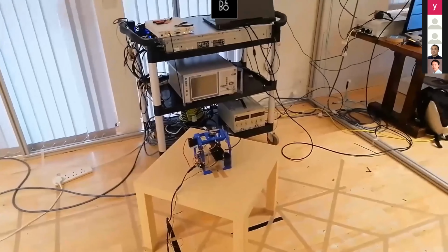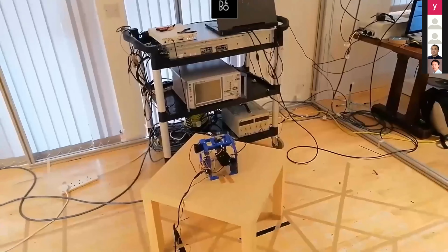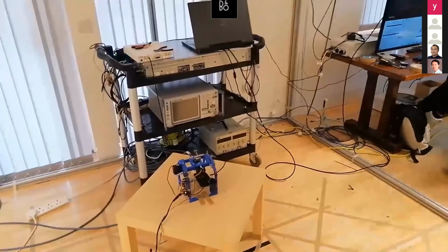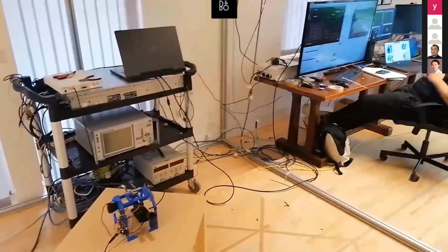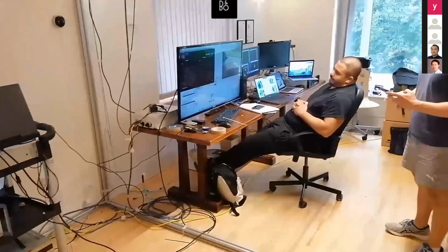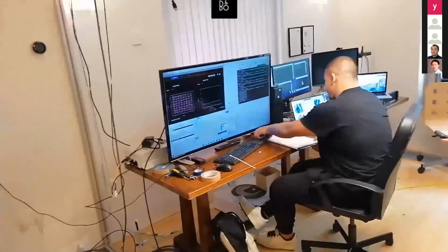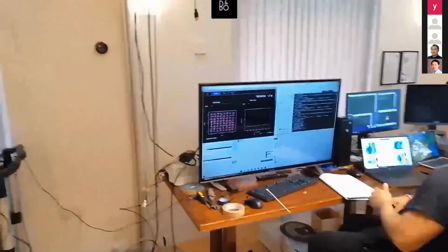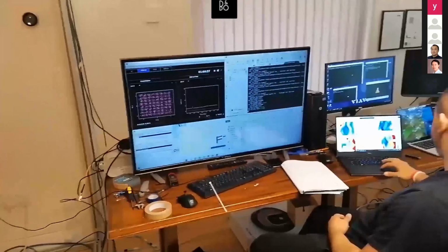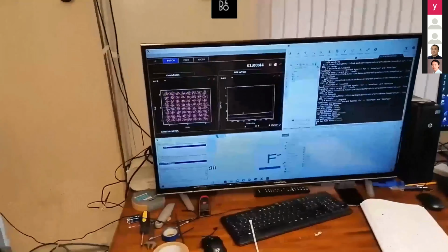The test receiver records 5G received signal strengths, QAM constellation diagram, mean and probability distribution of the error vector magnitude, the error vector magnitude evolution with time, the block error rate and throughput for the physical downlink shared channel, the physical broadcast channel, and the physical downlink control channels. Here you can see the millimeter wave recording being taken at tabletop height, 0.7 meters, and the performance of the received physical downlink shared channel signal being recorded by Karim, who is one of our researchers.